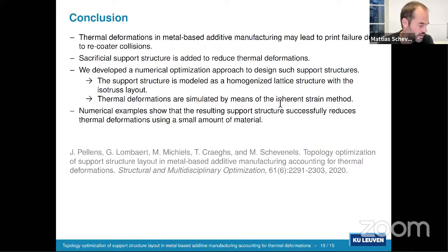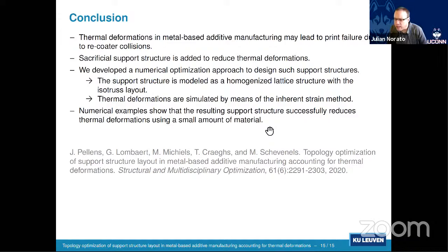For the 3D case, it was about 4 hours, but it's quite a coarse mesh. In fact, we only used 150 elements lengthwise, and then 20 by 20 in the other dimensions, and it was 4 hours on a laptop. Okay. And the other question from Dirk is, how confident are you in your interpretation of the results? So is the algorithm convergent?